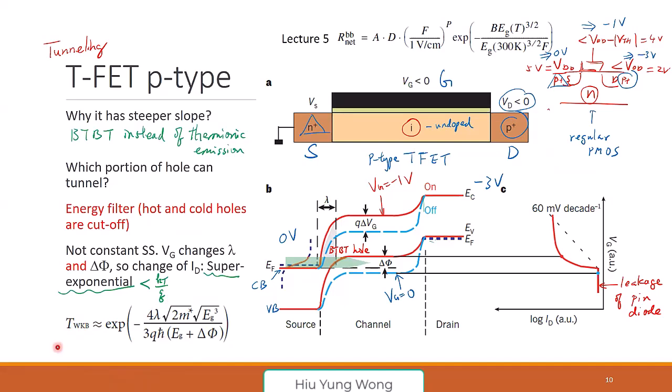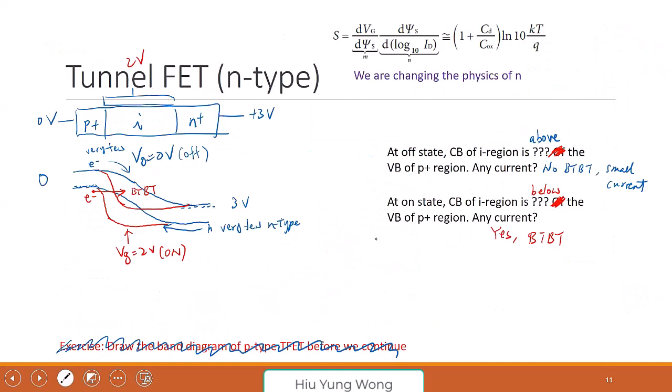But now you should know that the WKB approximation tells that the tunneling is more if you have a thinner barrier, and if you have a smaller gap. When this is higher, then the barrier height is less. And that's all. This is about the theory of the tunnel effect. Any questions?